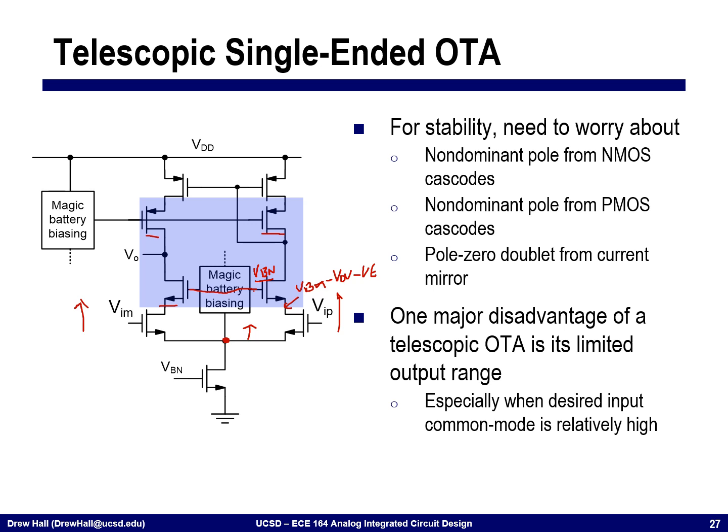And so typically what that means is that you will sink some current into this device, and that means that we will also need to pull the current out of this tail node in addition to what we would normally have running through both sides of this. So this current that's going to come out of this tail, or this node here, is I tail over 2 plus the bias current, okay? And so usually what you'll see is you'll see another transistor, like in the common mode feedback case down here, in order to pull that bias current through this.